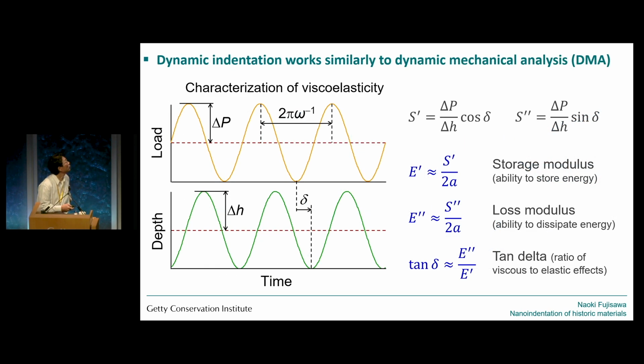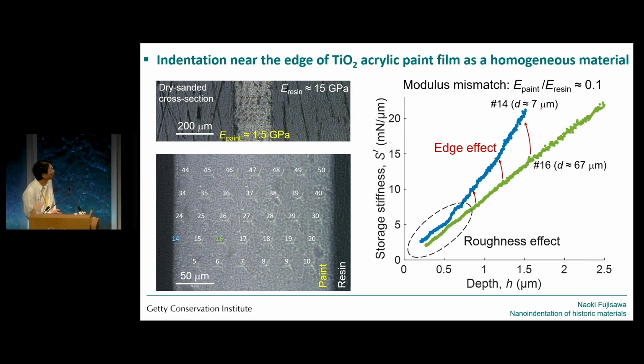And so this dynamic indentation also allows us access to viscoelastic properties of the materials. And the principle is identical to DMA, but a lot of experts of this technique have already covered this topic. So I'm going to the next slide.